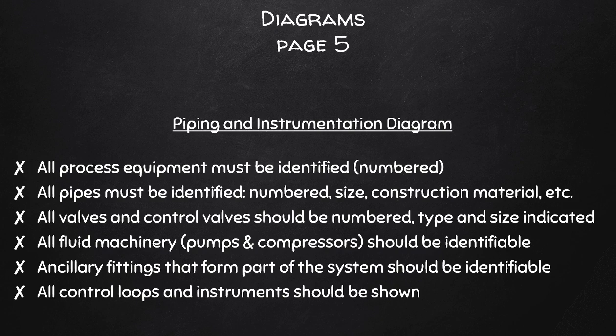I cannot tell you how many times I have seen in design reviews a cutting mill being specified by some final year students, but I see on the page a hammer mill being used instead. So please make sure you use the right symbols for the right unit operations, because we will most definitely pick this up and ask you lots and lots of questions and hopefully embarrass you with the intention that you learn from it and that you know better.